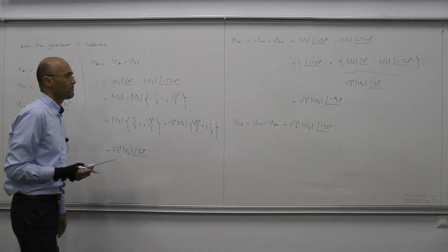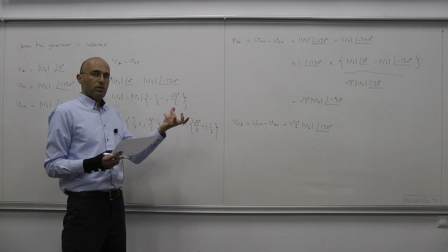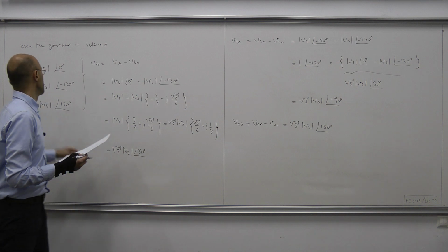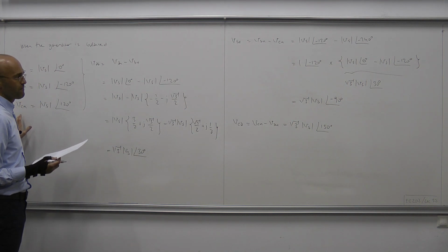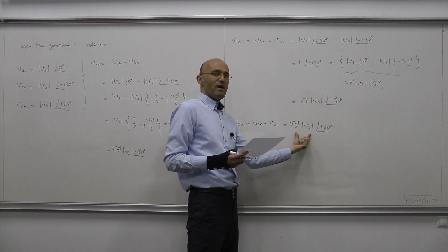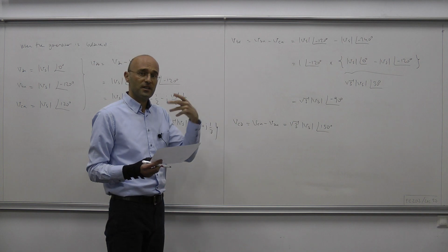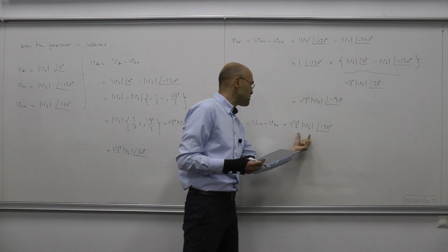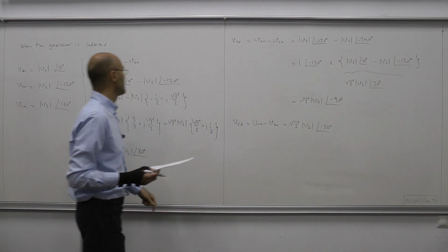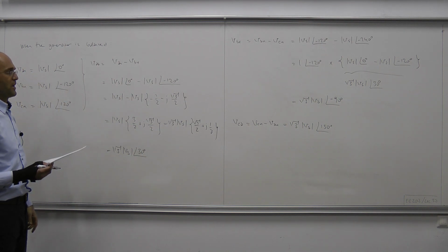Now we can compare them with the triple of phase voltages, namely VAN, VBN, VCN. As for the magnitudes, each line-to-line voltage magnitude is the same, and it's square root of 3 times the line-to-neutral voltage, for the Y connection.